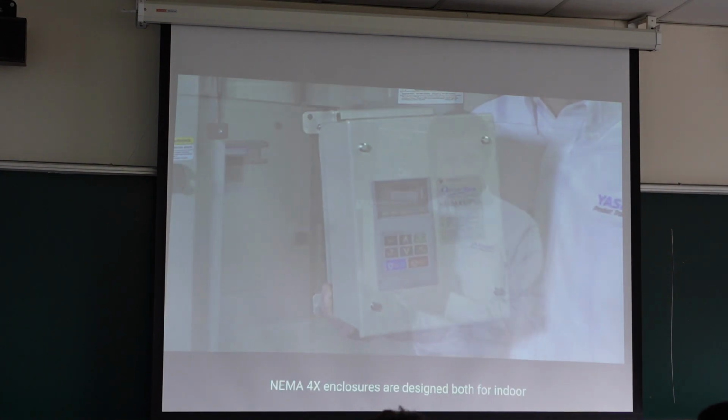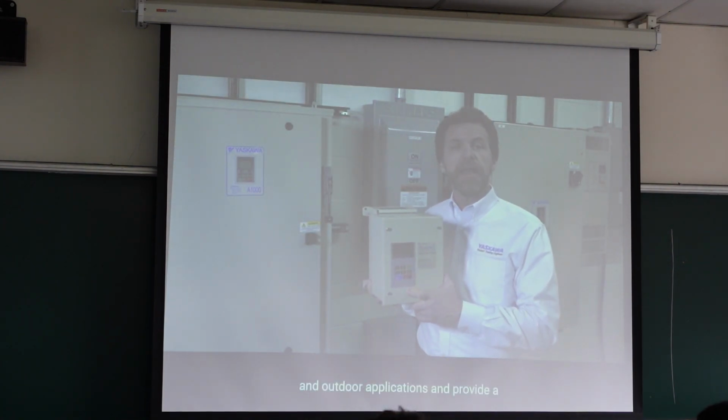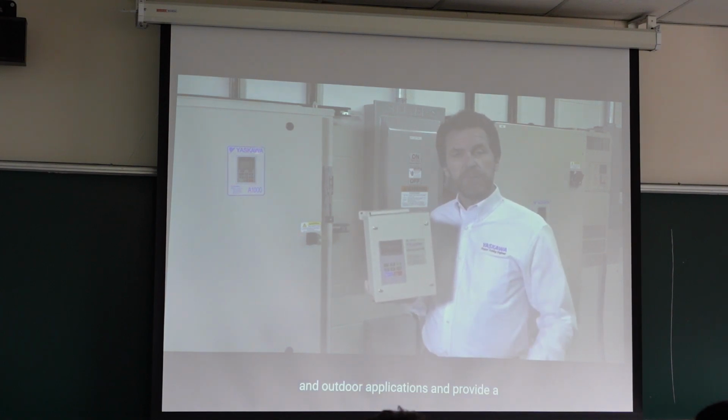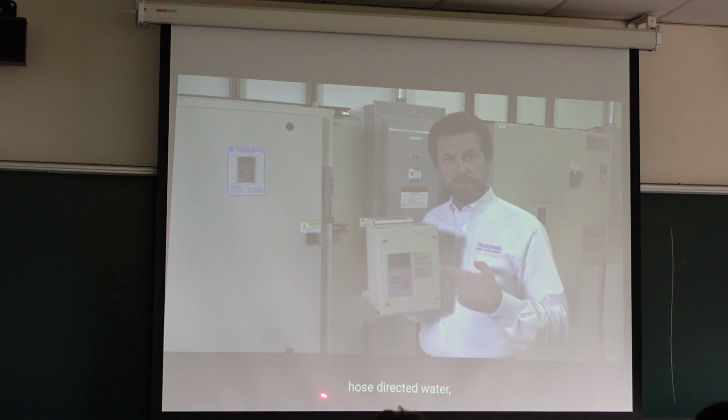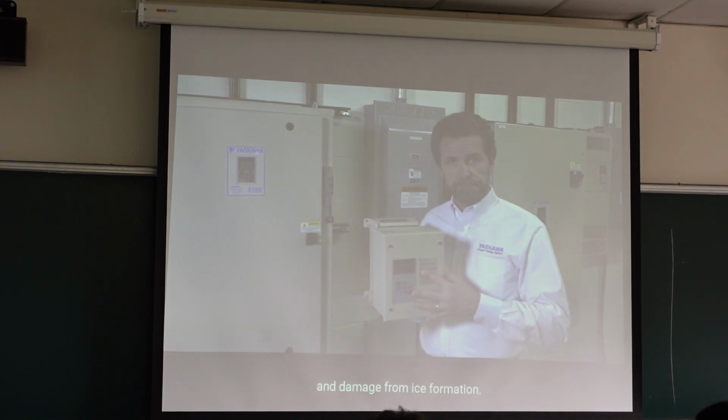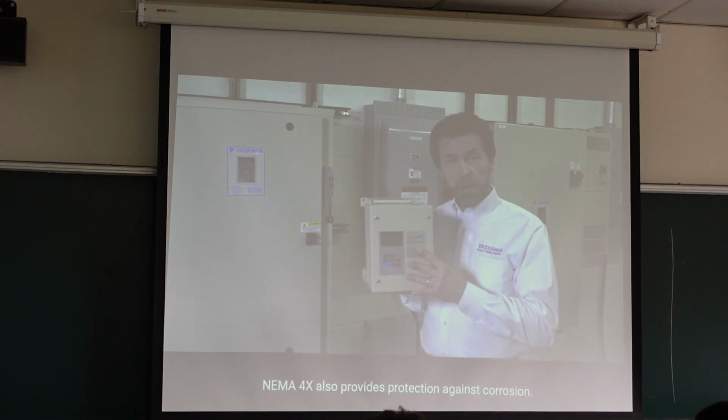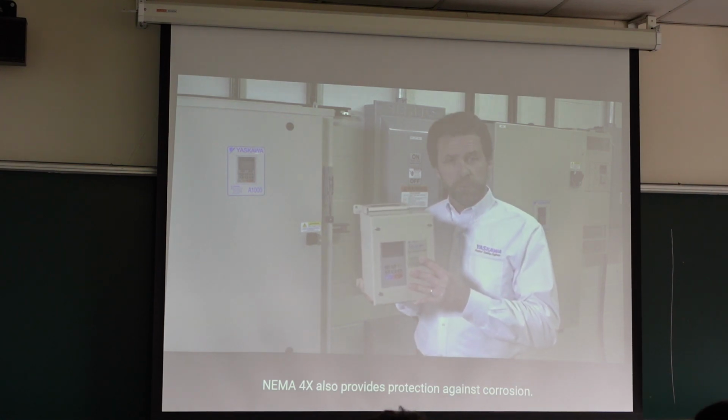NEMA 4X enclosures are designed both for indoor and outdoor applications and provide a degree of protection against falling rain, hose-directed water, and damage from ice formation. NEMA 4X also provides protection against corrosion.